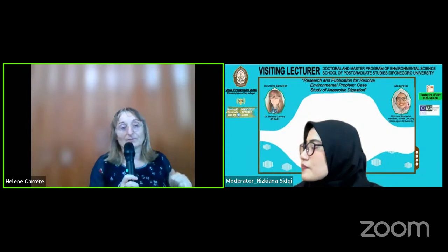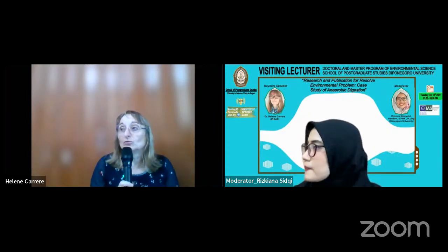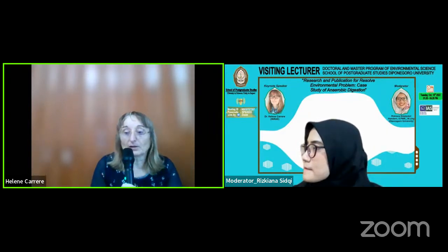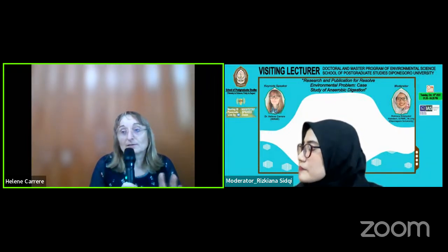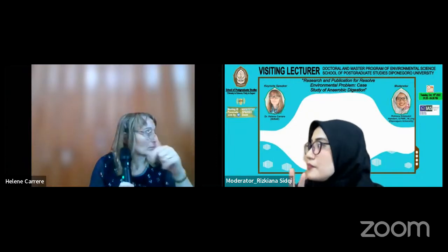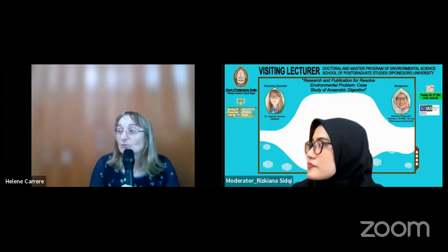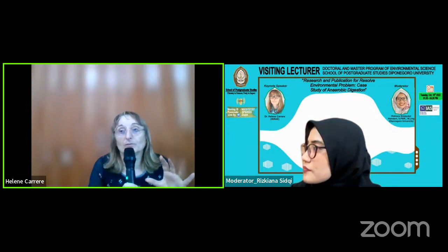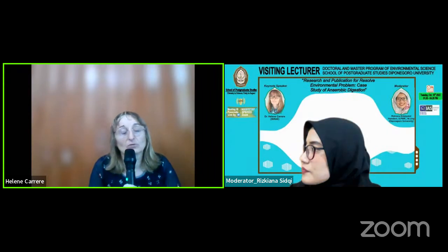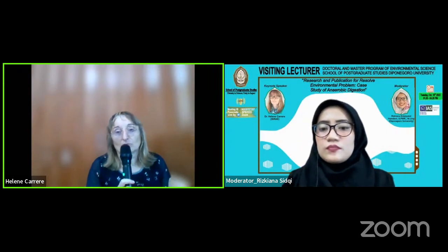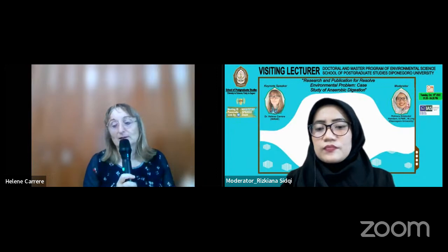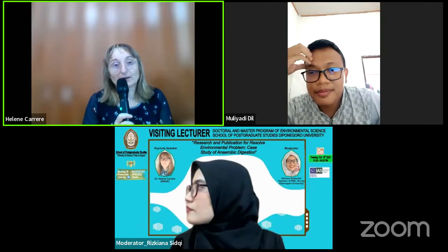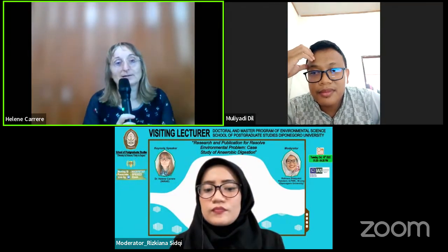If you want to remove the methanogens, you don't want any methane, there are several solutions. You can treat your inoculum by heat shock, thermal treatment at 90 degrees, so you will kill the methanogens, the pathogens, and also you will favor the Clostridium, which are spore-forming.